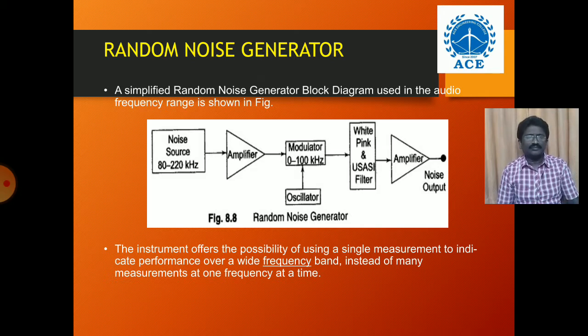With the help of the upper current source and lower current source, you can change the position of the current levels. With the help of the integrator, you can generate a triangular wave, and with the help of the triangular wave you can make some modifications. Finally we get our required sine wave, square wave, and triangular wave with the help of the function generator. In the last class I gave an explanation of the function generator. I have given some video also.